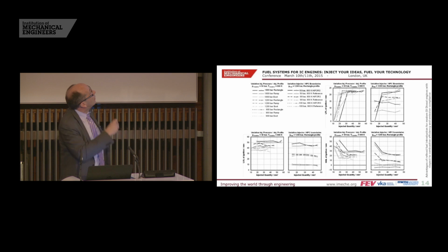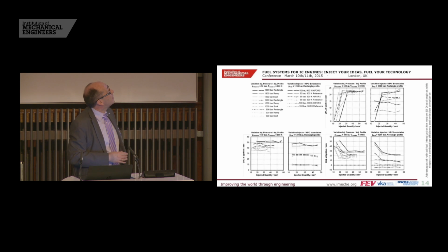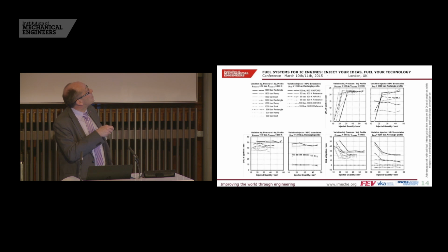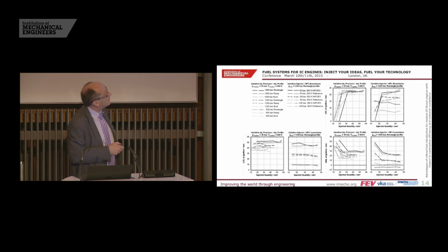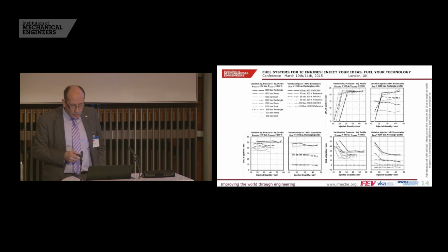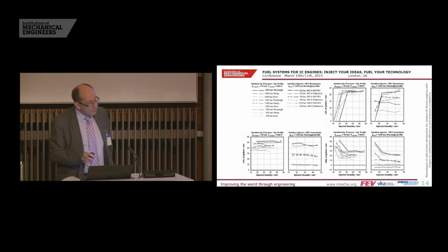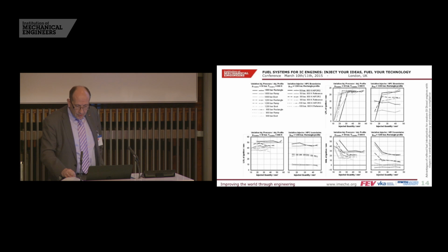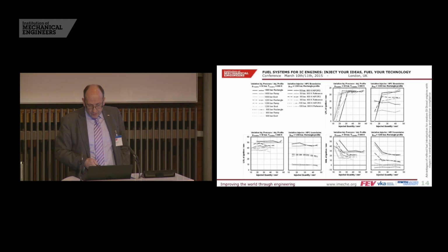Only for completion, as I said, a wide matrix of investigations of different configurations, either from the injection profile, as I said, different injection pressures, different injection profiles, but also different boundary conditions in the high pressure chamber were investigated. You can read more about the details regarding these typical parameters which we summarized here, like the lift-off length and the liquid penetration length. You can read this in the manuscript, which is in your hands, so I don't have to go into more details about this.